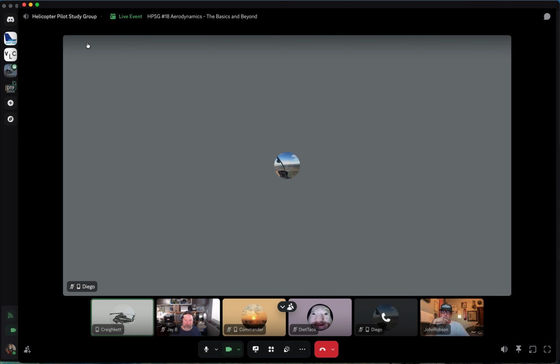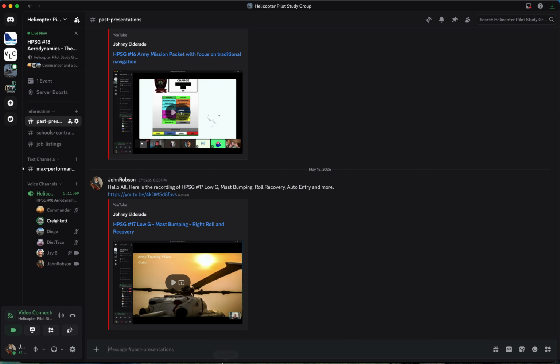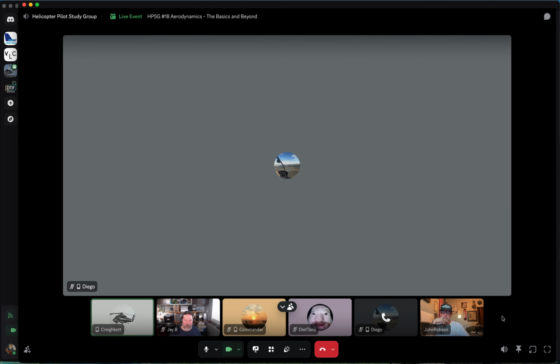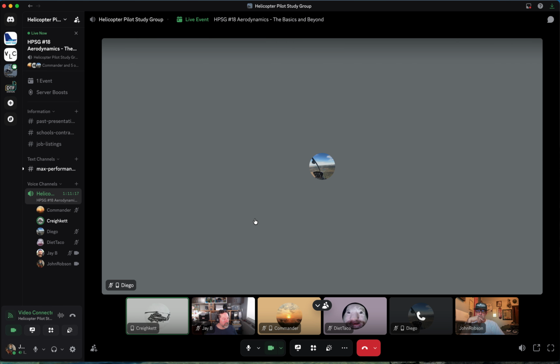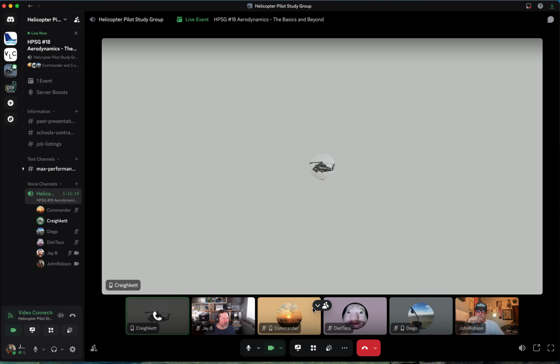It's just, this is your lift to drag max, where it's most efficient. I don't usually go into much more detail than that, right? And just letting them know that's why we climb at 53 in the R22, or 55 in the R44. Why we have that center line basically of all three of those drags where they meet. Yeah, but that's about it.